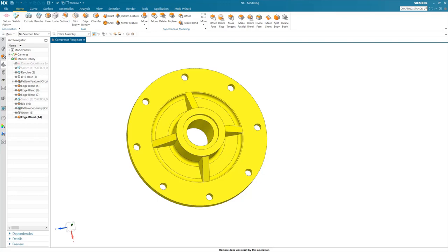In this video, you are going to learn how to create drafting standard inside NX-CAD software. By using drafting standard, you can save your drafting preference such as line thickness, arrow style, text size and font. You can also create multiple drafting standard, for example, one for tooling drawing and other for part drawing. So let's start this video.